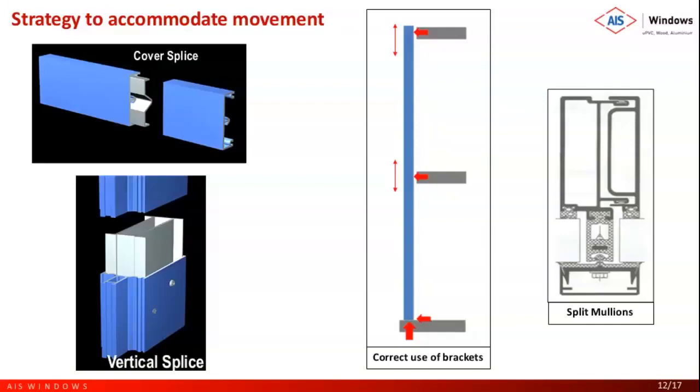Similarly, on the mullion side, the vertical splice plate is used. I've seen many places where people tend to screw on both sides, considering that this makes it stronger, but that is a misunderstanding some people have. This joint is specifically made to absorb the movement. So one of the mullions should be free to slide up and down.